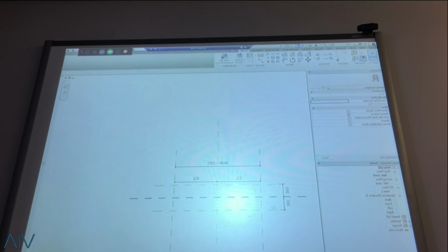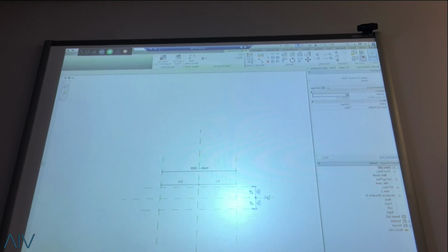Because there's a chance that if you put in some other weird number and then hit equal, this offset will shift and screw up your family when you load it in. It's one of those things that a lot of new users who want to build a family don't understand. Because once that offset is shifted, sometimes your door no longer has that origin point, and then you have to figure out, calculation-wise, what the offset is and counterbalance it. It's a very messy process. So if you want to keep it consistent, do it like this.